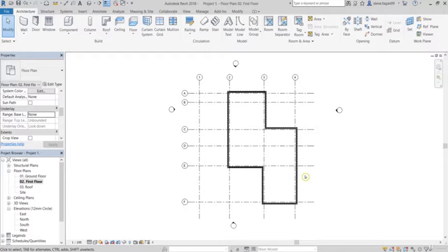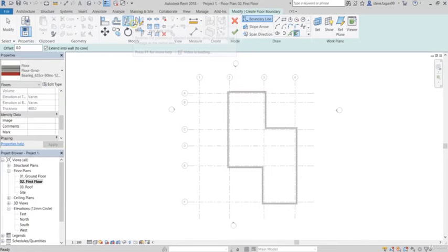Now that we have our clear working space, we can create our first floor slab. Same process as drawing in the ground floor slab. We'll go to our build panel. We'll select floor. Again, we have the same contextual tab. We must select one of these modes to finish, how we will draw it. We have our options bar with the offset and extend into wall core.